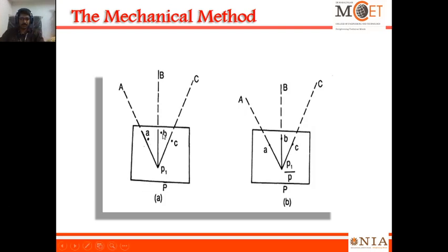So these points are all the points available on the map. I have set up my instrument at P. I don't know whether it's right or wrong. I kept the alidade on the point P, and sight A, drop a line; sight B, drop a line; sight C, drop a line. It may cross over the B, A, B, C, or may not. Mostly not. So all the lines have been drawn over the tracing paper only, right? Remember that point, tracing paper. Now such a map was obtained.